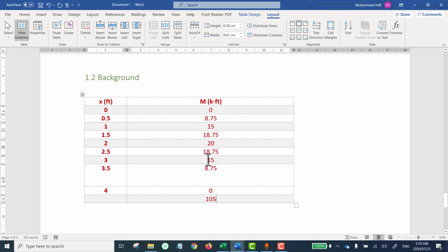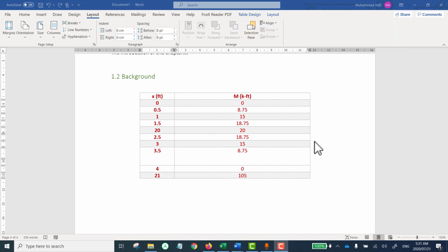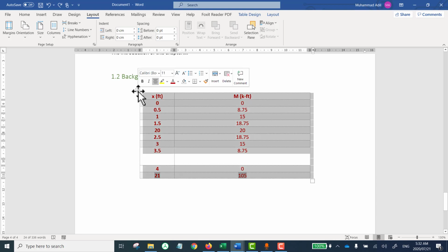So now if you change anything, for example this 15 to, for example, 150, you will notice that this sum has not changed. In order to recalculate, you either select this cell and press F9. If you have a table with many formula fields, like in this we have 2, you can select the whole table and then press F9 key to update all cells if you have done any change in the table.